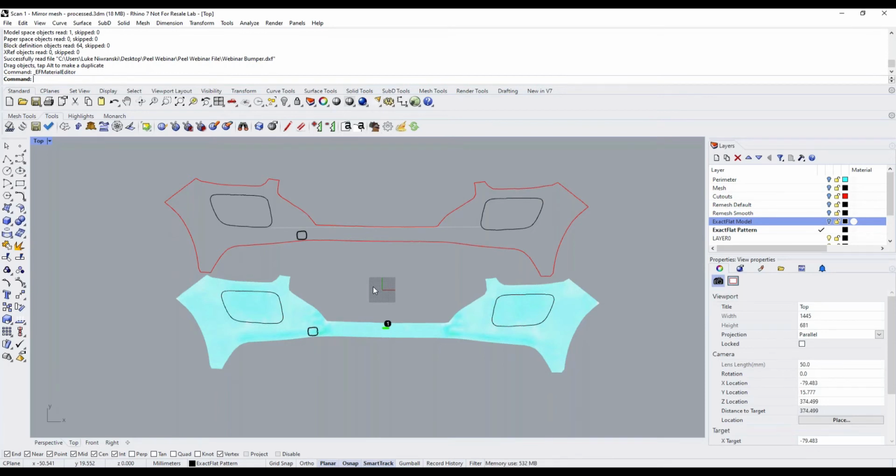If you're working with a very expensive material and it's very critical that you get the absolute perfect part right away, you might choose not to mirror the part. You might want to take the extra time to scan it. That way you have 100% confidence that the 3D model you're working with is a true representation of the part that you're going to be covering. That way when you do the flattening work, you're guaranteed that you're going to have the perfect fit. So there's a lot of different factors that come into play there: the complexity of the part, the amount of time you want to spend doing it, the material, and so on. So unfortunately, I don't think there's any guide that I can offer for when you should mirror your part or not. It would probably be on a product by product basis.